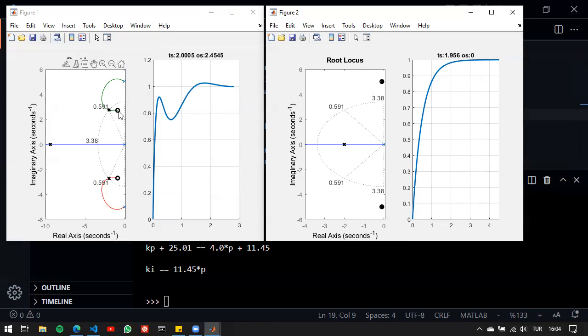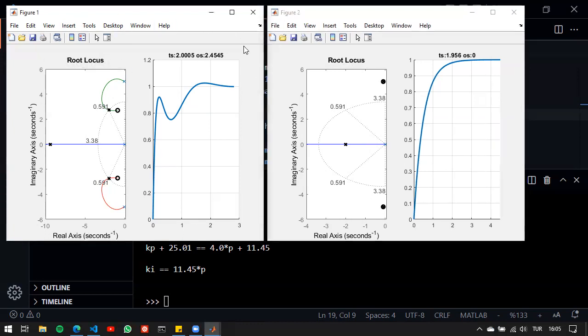So the question was, what if we place the zeros on the real axis? In the dominant region, we are not able to place zeros because we want to prevent that from happening. Outside of the dominant region is a good place to place some zeros. But that was not available in the tabulation method, and it's basically a numerical search. If it's not possible, then the numerical method does not give that. If it had been possible, we would have ended up in figure 1 with that scenario.